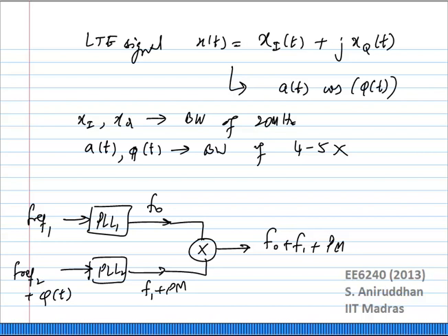For a moderate bandwidth, you can probably ensure an all pass transfer function, but the wider it gets, the tougher it becomes to actually ensure an all pass transfer function. So what you'll find is with many of these modern wideband signals such as wireless LAN or LTE and so on, pretty much IQ, the Cartesian upconverter, is the default architecture of choice.